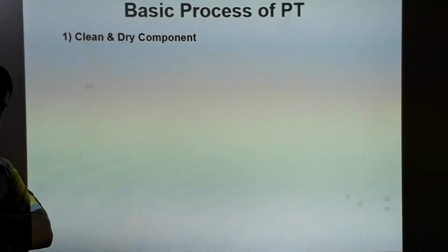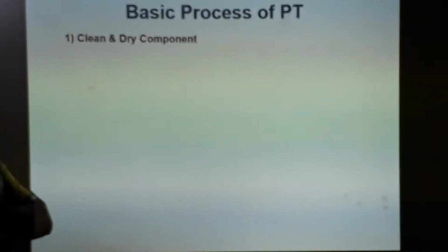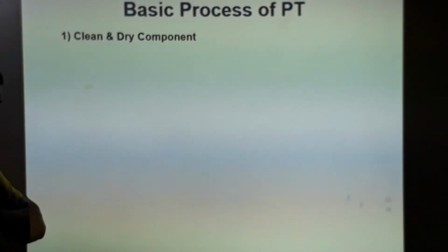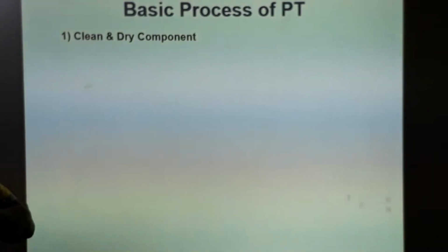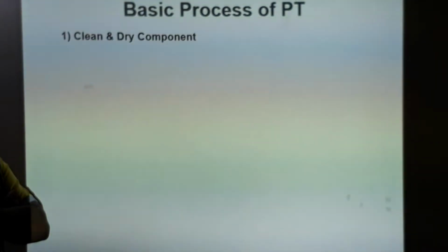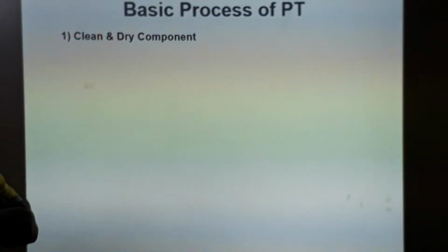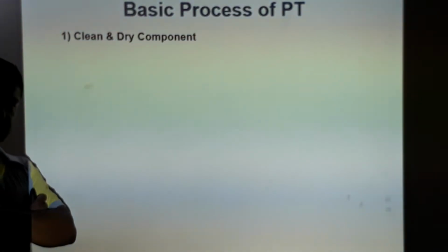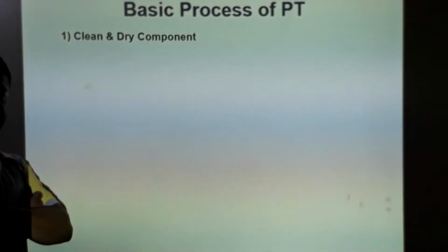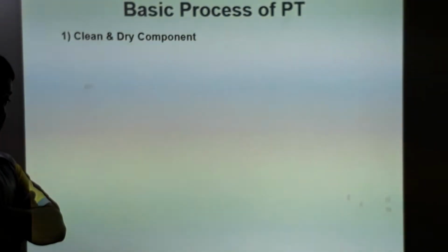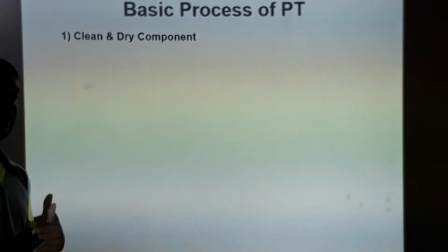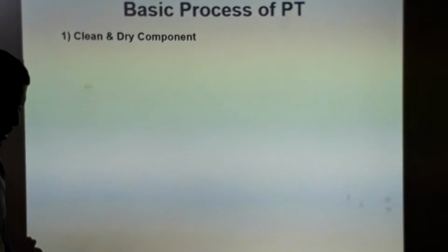Without effective pre-cleaning, the effectiveness of penetrant testing will be very low, because either you will be missing a defect that is countable, or you will be getting some irrelevant or false indications, or your acceptance of indications during your acceptance stage may go wrong.